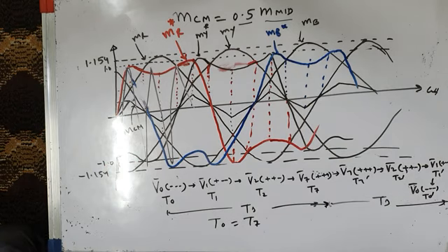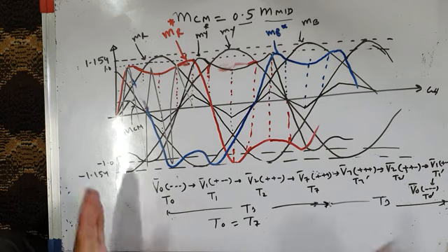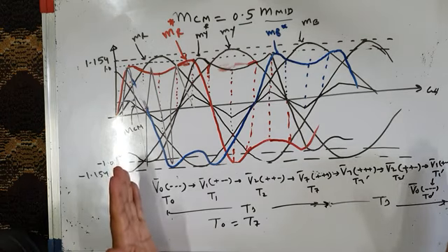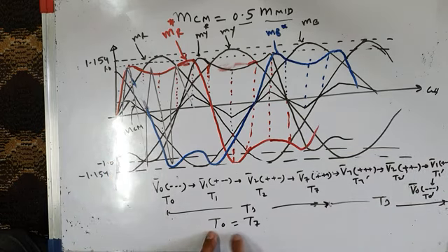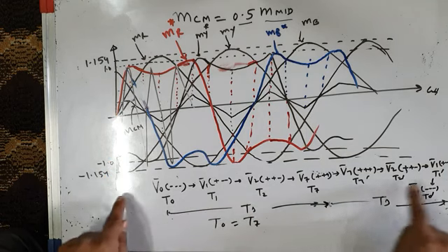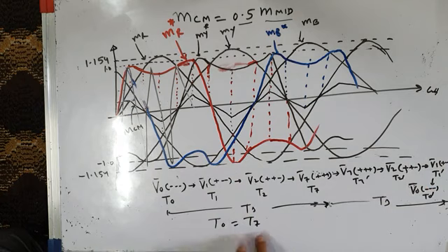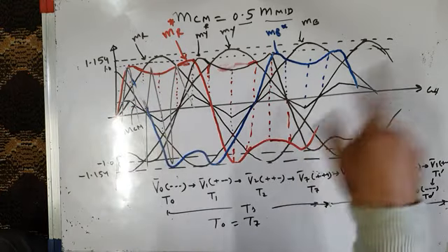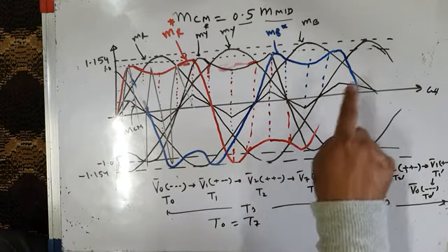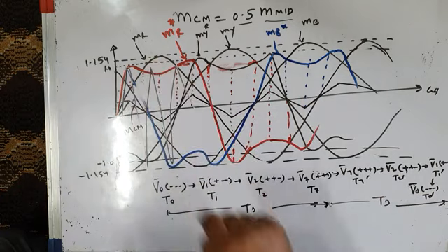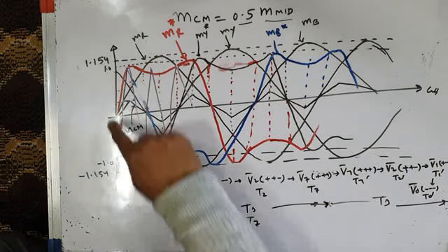we can say that the space vector PWM technique gives this switching sequence in a particular sector, that's sector 1, and also gives T0 equal to T7. Sine triangle PWM also gives the same switching sequence in one carrier cycle, but it does not give T0 equal to T7. Null vector times are not equally distributed. But when we use triangle comparison, not sine triangle comparison, but triangle comparison based PWM, in which our modulating waves were not sinusoidal, they were distorted like this.